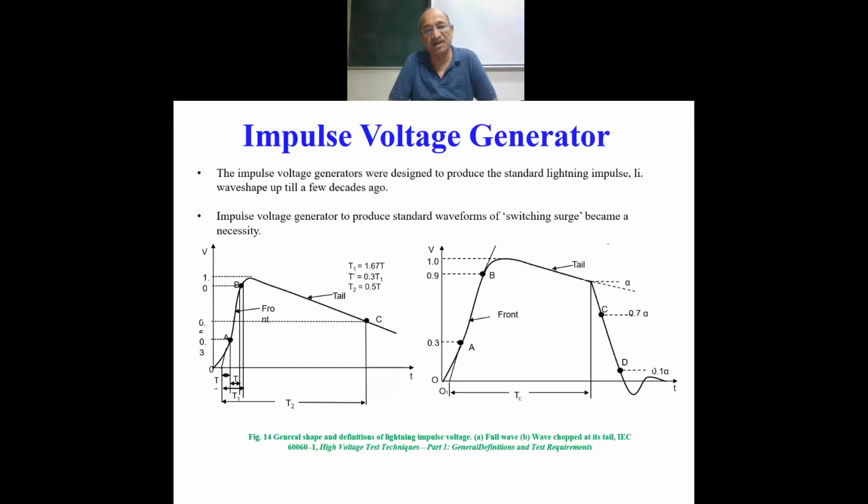Transient over voltages last very short, as you have learned, and there are two types of transient over voltages: lightning and switching. Lightning is a very, very fast wave. It's just a wave. It's like a pulse, and it travels like a pulse, and it affects the insulation wherever it travels through. Let it be insulators on the transmission lines, let it be when it reaches substation. Mostly the first equipment is the transformer, which becomes very vulnerable, and other equipment in the